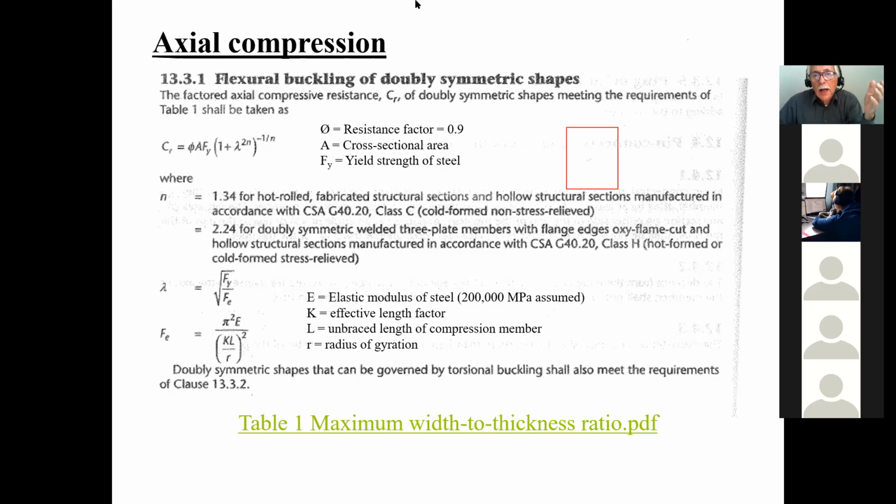Now, what happens is that in steel, because it's very, very strong, these plate elements, when they're in compression, they can fail locally. And by failing locally, as they add more strength, instead of you being able to take advantage of the whole cross section to give you resistance, this thing fails and the whole thing's going to collapse. So in steel, it's just to make sure that these plate elements aren't the ones that are going to govern the overall resistance of the member.